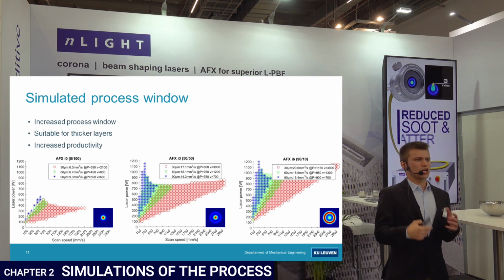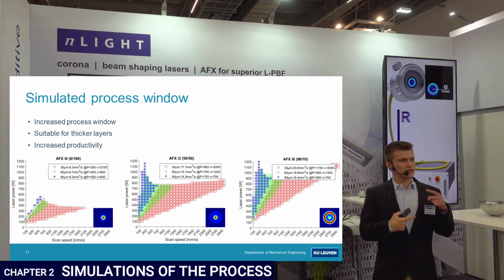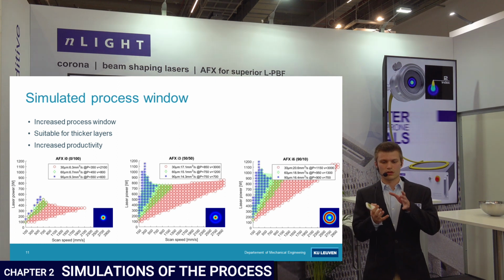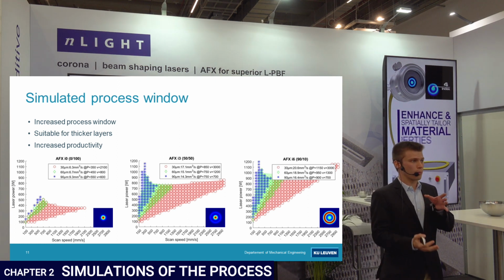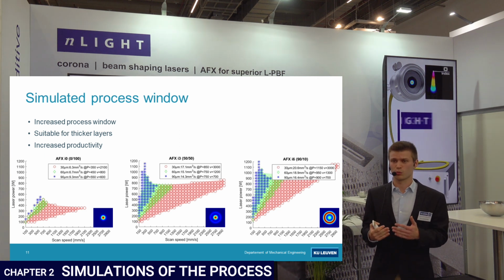You would say it's a shallower melt pool, sure, that's quite counterintuitive, but you have to think of it the other way around. Because we decreased the depth, we can put more power in the system before we reach the keyhole mode melting and the corresponding keyhole pores.